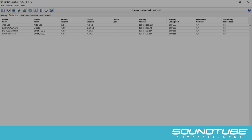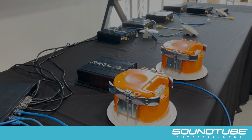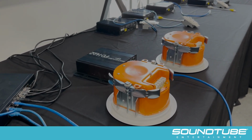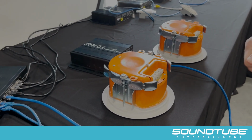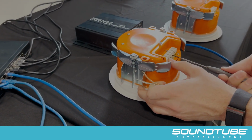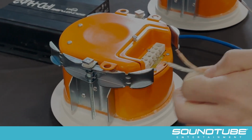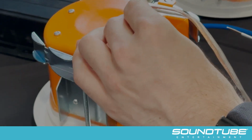Now that we've changed the name, we can go back into the STNet Control Center software and refresh the device list. We're now ready to wire our first set of speakers. Each IPD-Hub 2 amplifier has 2 8-ohm speaker outputs, meaning you can wire 2 8-ohm speakers to it or 4 16-ohm speakers. SoundTube speakers are preset to their maximum 70-volt tap setting out of the box.